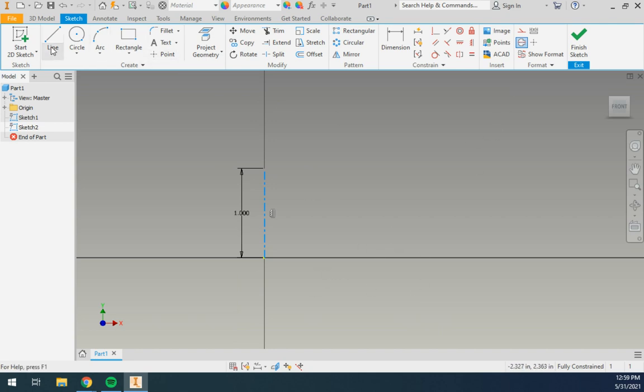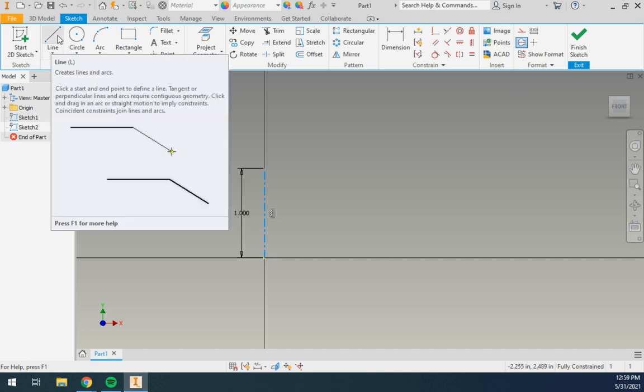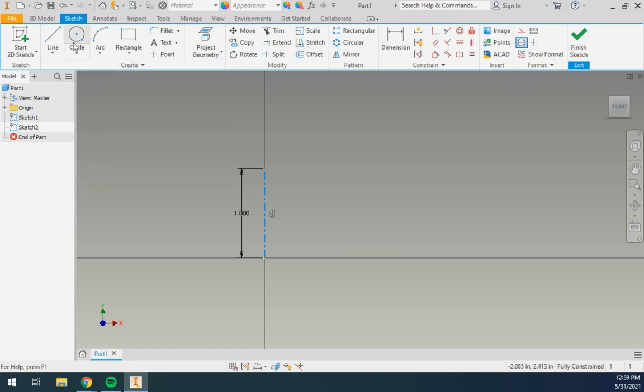I'm going to make what we are going to refer to as a little bit of a washer with some different features to it. But understand it's still going to rotate around this axis. So now I'm going to go back up here, select my line tool, and create basically just a simple profile. I'm creating this with no real dimensions right now because of time constraints. I'm going to go up, line this one with my axis there, and create just a simple flanged washer of some sort. Again, this shape is up to you. You are the one behind this one.